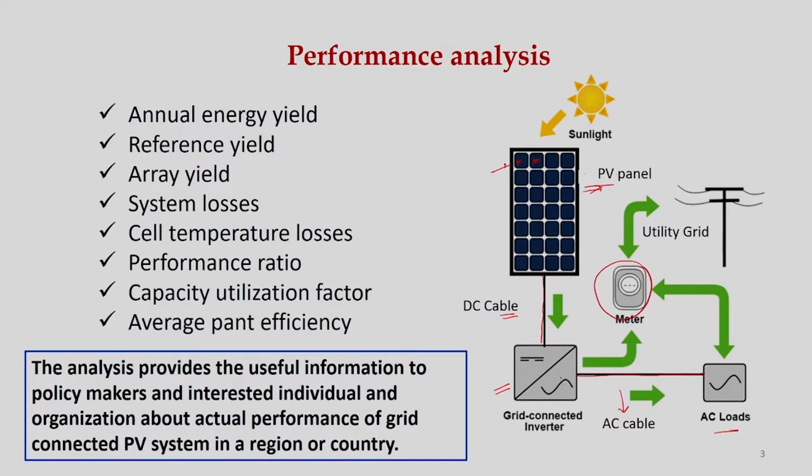Suppose we are not using the generated energy, then what can we do? We can give the generated energy to the utility grid, and maybe at night when demand is there, we can take it back from the grid. That way we can use this grid connected PV system.